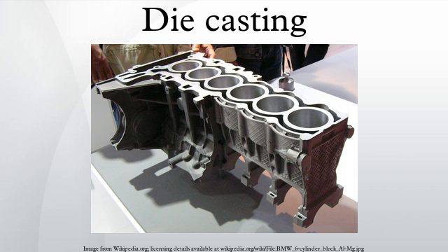The Acrorad system was the first die casting process that could successfully cast low-iron aluminum alloys, such as A356 and A357. In a traditional die casting process, these alloys would solder to the die. Similarly, Acrorad castings could be heat-treated and meet the U.S. military specification MIL-A-21180. Finally, the Acrorad system employed a patented double-shot piston design.